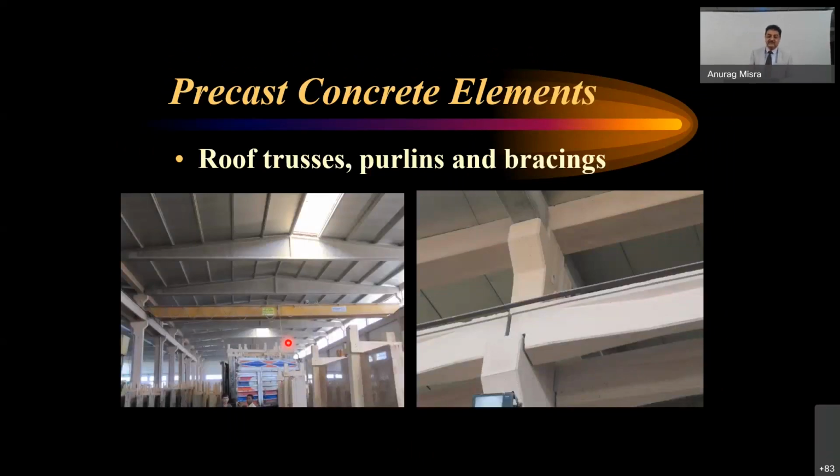Then we go to the wet cast plant. What I'm showing you here is completely precast concrete. In this, even the columns are precast, nothing is cast in situ. All the beams, even these truss-shaped rafters, are precast. They are created in the factory and brought to the site. There are mechanisms by which these are placed in position with a proper keying mechanism, and your erection is complete in no time as compared to cast in situ.